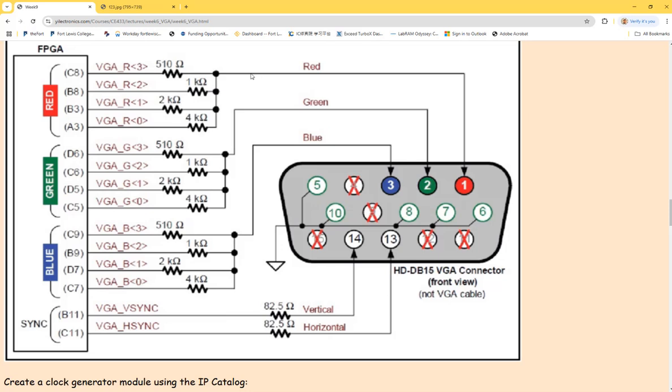So that is why the voltage is dropped across the 300 ohm resistor instead of the 1K. So definitely this one will give you less weight. If you put a 1 here, your output voltage will be less than if you put a 1 here. So definitely the MSB has more weight compared to this bit, and so on and so forth.